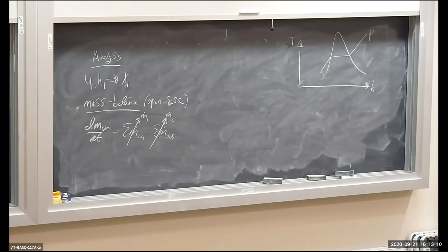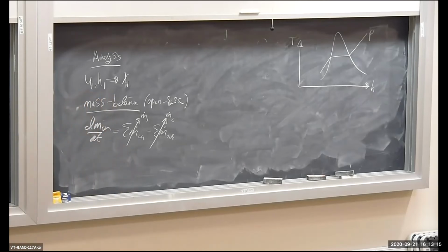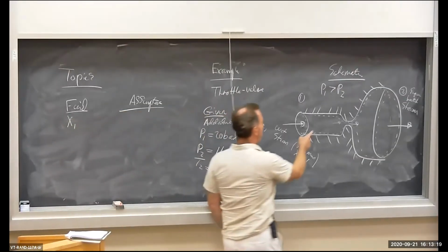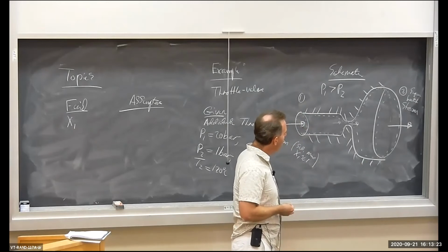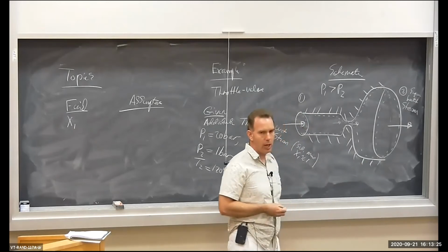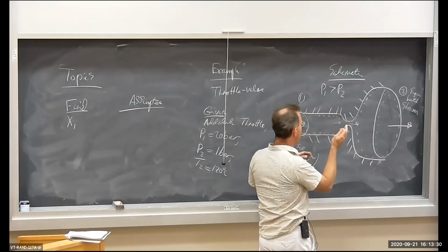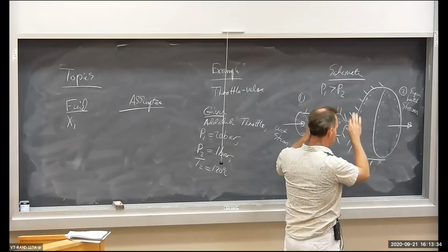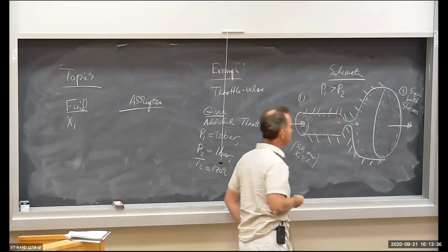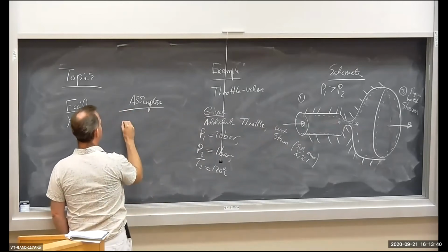Now, what about the time rate of change of mass within my throttle valve, my control volume? Well, there's nothing in the problem about time dependence, about the flows in and out changing with time, or about mass building up inside the valve or depleting in the valve. So I'm going to assume steady state, steady flow.